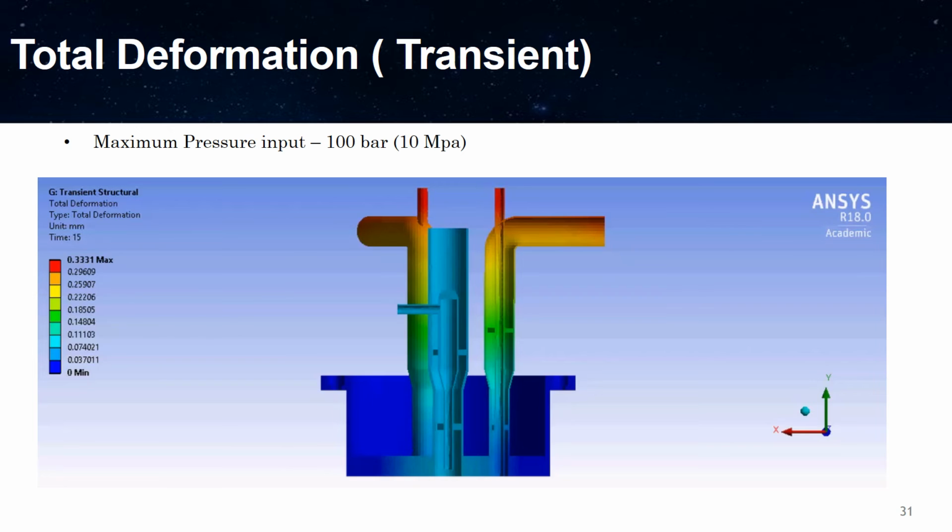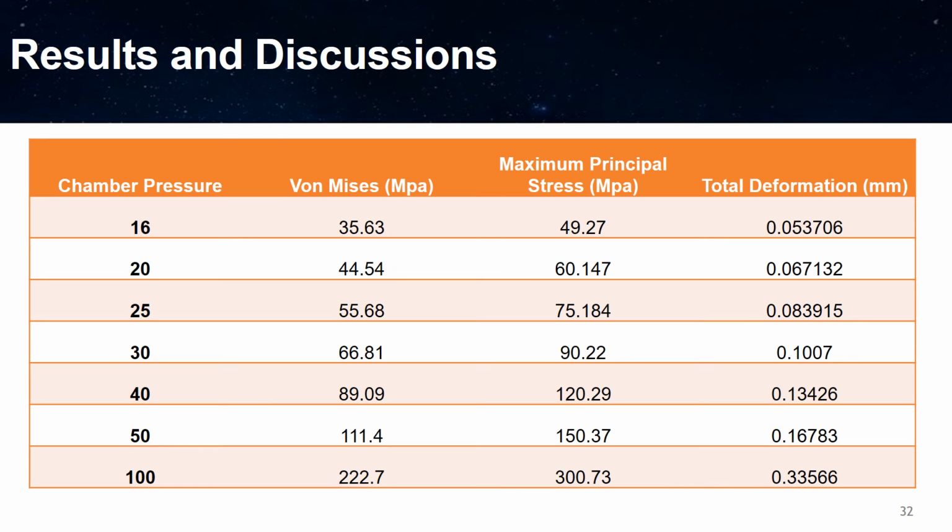Otherwise, for the whole injector, the deformation along the outer walls is fine, because that is experimentally observed during experimentation, and it can go up to around quite a few millimeters of deformation before basically plastically failing. So we can live with it, but we need to look closely at the support structures when we redesign it.